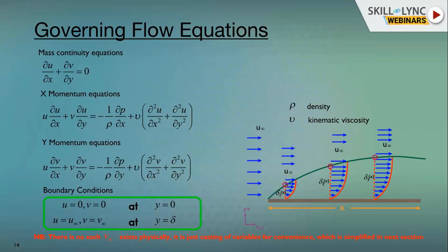The kinematic viscosity gives an idea of the depth up to which the disturbance of the boundary layer propagates. Even if there is standstill water on the surface, you generate some disturbance. How deep the disturbance will propagate is somehow related to the kinematic viscosity. And how it is related, we will see in the next session. And the dynamic viscosity is related to some property of the fluid that is called viscous dissipation.